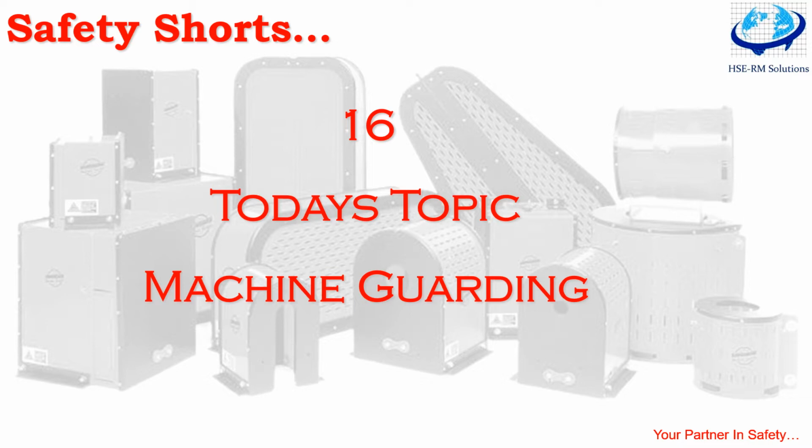Yes, in true sense, where machine equipment has an exposed moving part and running nip hazard, or a material being processed in a way that creates a point or a hazard, the machine should be equipped with guards or other devices that prevent access to the moving part or pinch point.